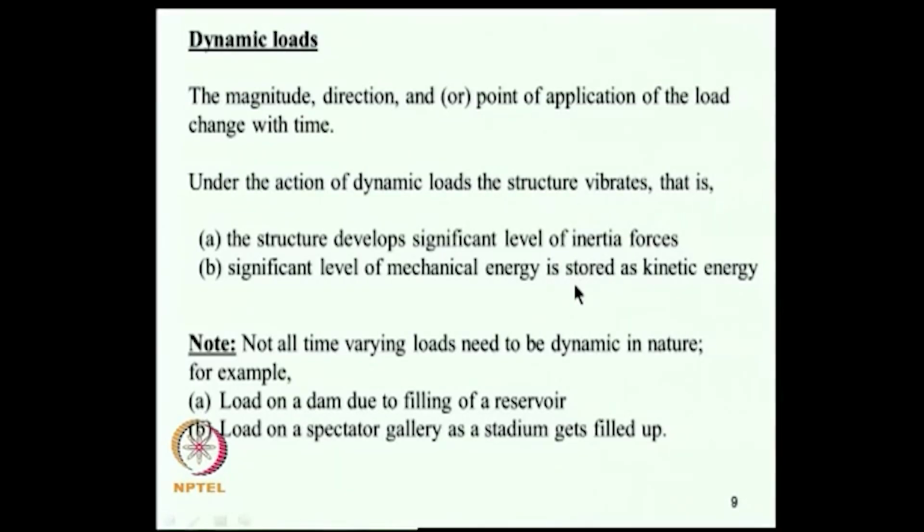In a static problem, the work done by external forces is stored as strain energy, but in dynamic problems, the work done by the time varying load gets stored as not only potential energy, but also kinetic energy, and there is a perpetual exchange of one form of the energy, that is kinetic energy to potential energy, and that is what we call as vibration. Added to this, there is one more source of energy, namely the energy dissipation. So, that we call it as damping.